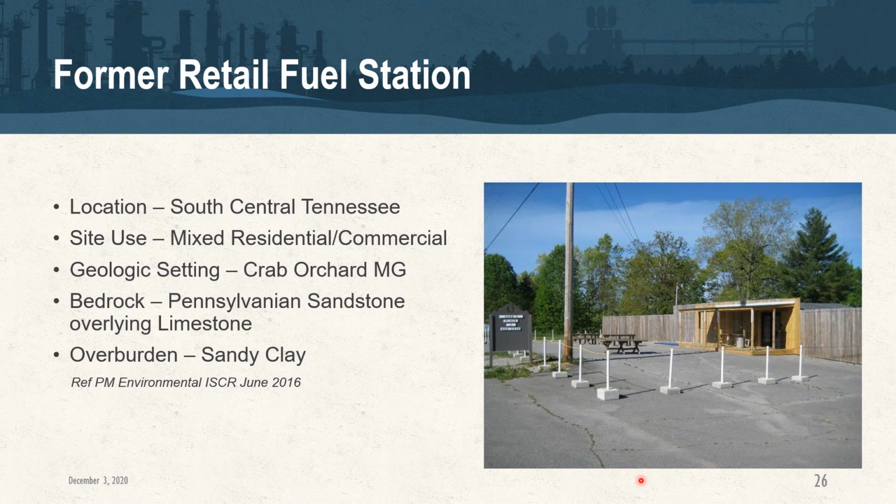Yeah, so we're going to try and be conscious of time here. I know we're getting close to the end of our time here for presenting, but I'll walk through this case study here. It's an ongoing remediation project that we're working on currently. It's located in South Central Tennessee, and it's a mixed-use residential commercial. Geology bedrock is going to be a Pennsylvanian sandstone overlying limestone with a thin residuum of sandy clay on top of that bedrock material. Next slide, please.